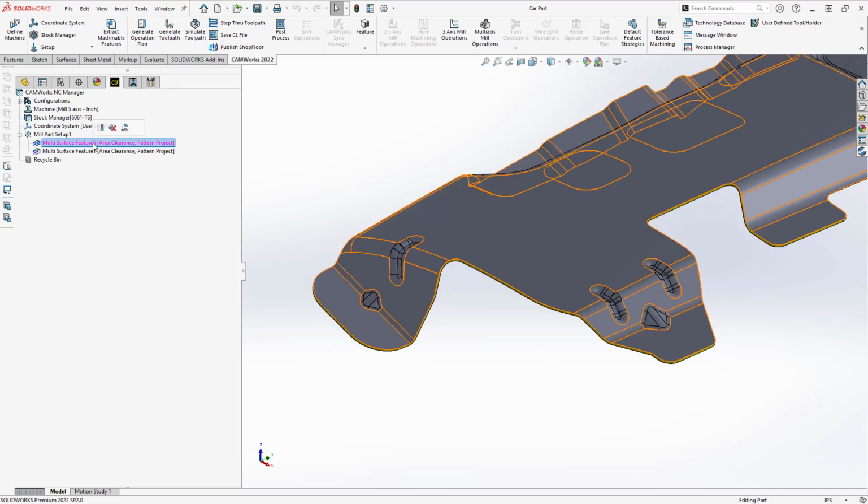Feature 5 is all the top surfaces. I'm actually going to be using this twice. I'm going to use this to define the trajectory of my 5-axis toolpath, but I'm also going to use this later as my gouge checking surface.